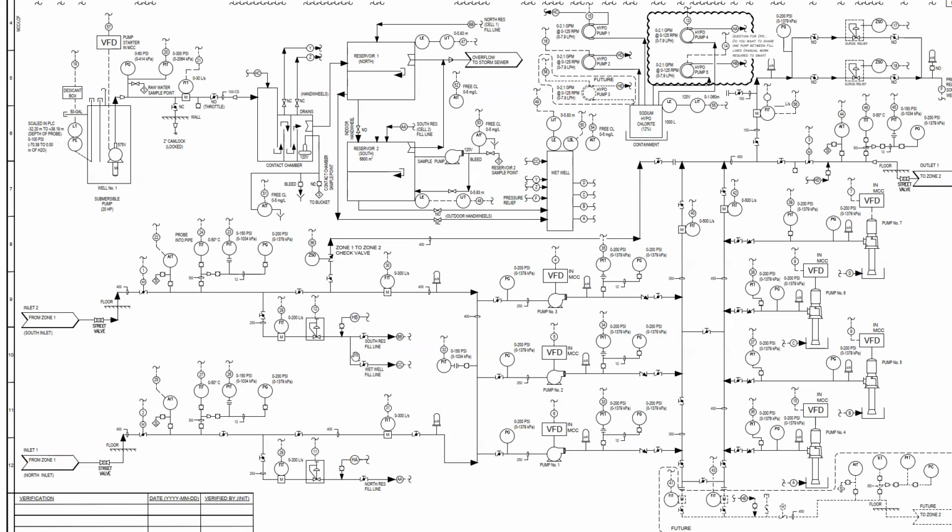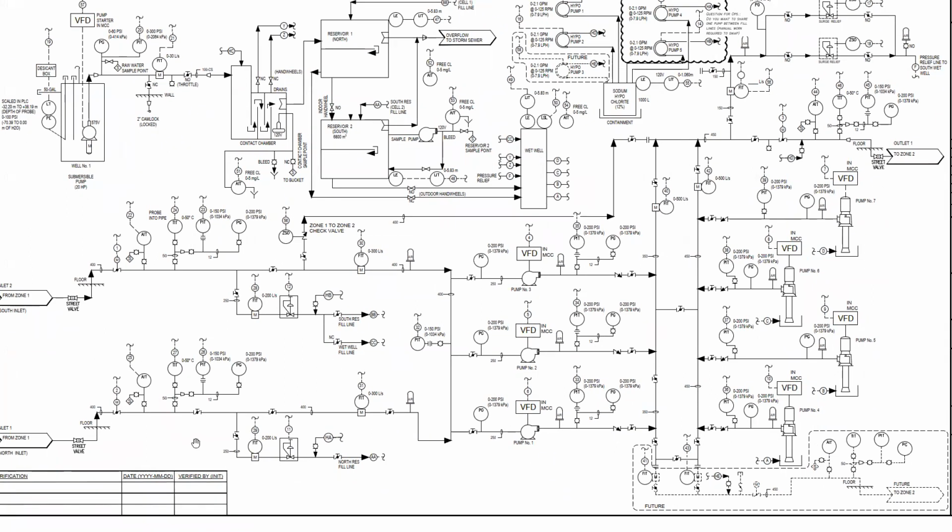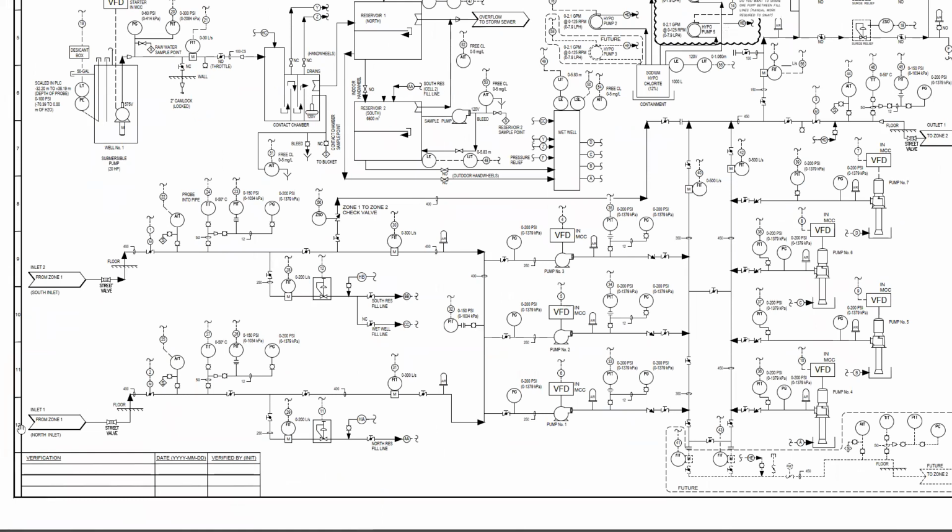South and north, south lines and a wet well fill line. And the other inlet that comes in does the same thing: chlorine, temperature, pressure, flow into the other reservoir. And then the water that doesn't get diverted into that reservoir will come here. We have a flow meter on either side to come into the booster station. The water will flow down. We have air release here as the pipe actually curves up, moves down into this header.